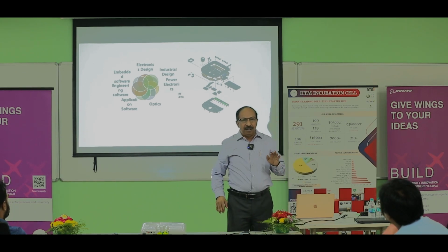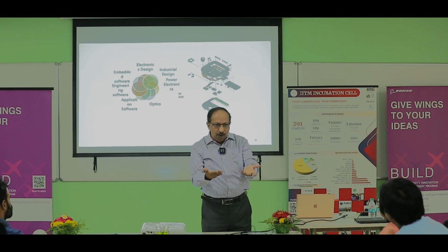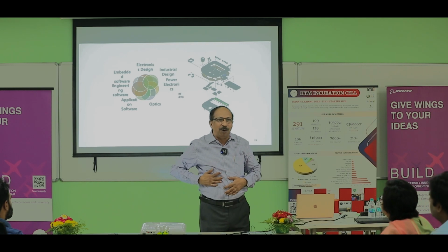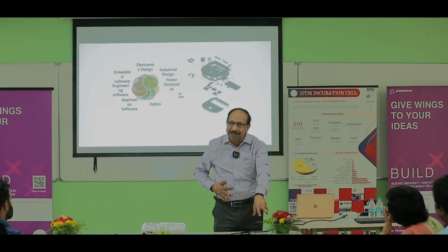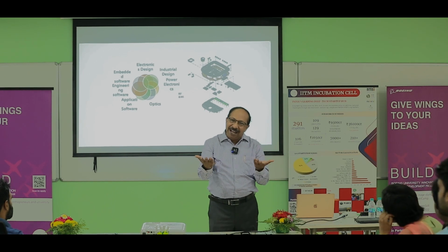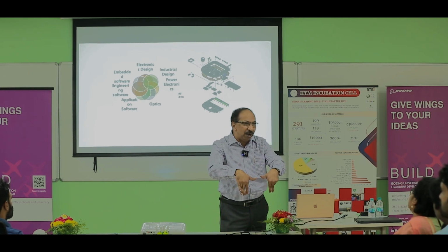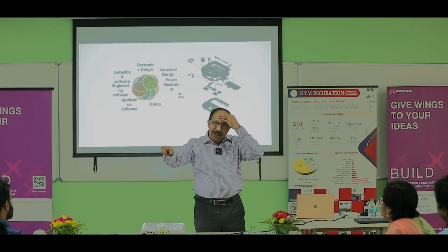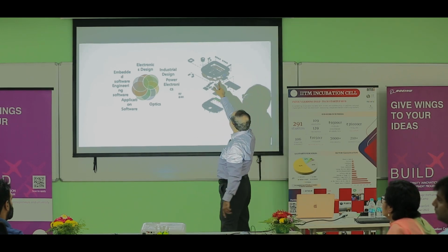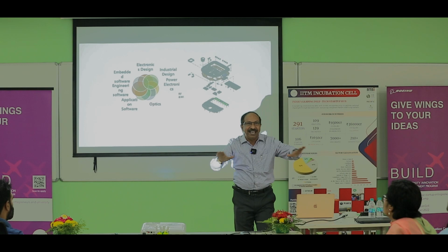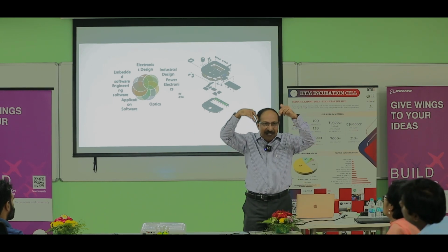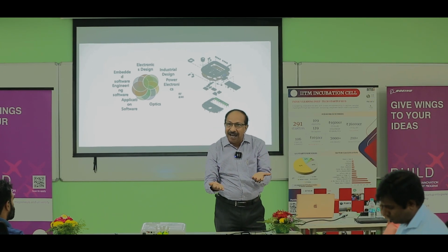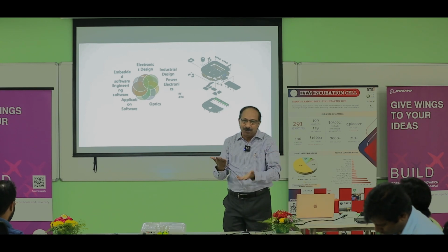You never think about how the ultrasound will be used. Those who have undergone an ultrasound can see that a lot of gel is used before putting the ultrasound, right? So that gel may fall on this console. Then water, coffee, whatever, and cleaning liquid, everything can fall on the console. If I don't think in that way, like this can fall, I have to take care of that. So what I have done is I have put a rubber layer there, so that even if something falls on it, it will not get into the electronics inside. It is drained through that rubber part, so that I will save my electronics. So you have to think of this.